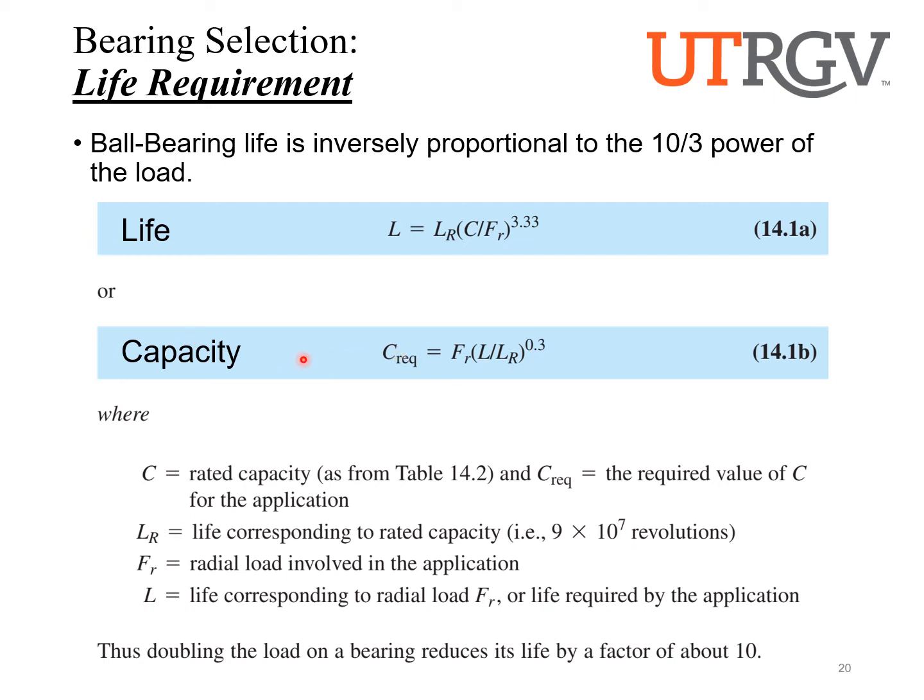So that's the second formula. The first formula is maybe I have a bearing size, and I know the loads that the bearing can take. How much is that bearing going to be good for? That's the bearing life. So we're typically solving for either one of these two, and these are going to be the formulas. I say baseline formulas because we're going to add in the next couple of slides some other factors that are going to help us account for more information. But these are going to be the starting equations.